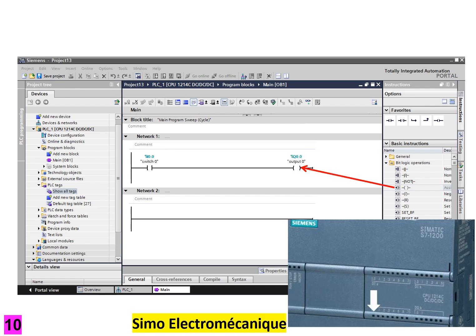We can then click and drag a normally open output to the right-hand side of the ladder, as shown. Click on the red question marks and enter Q0.0. This means we want the first digital output to be driven by this circuit. Q0.1 would be the second output, Q0.2 would be the third, and so on. We can now download this simple program to the PLC.